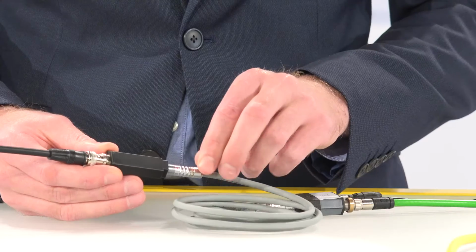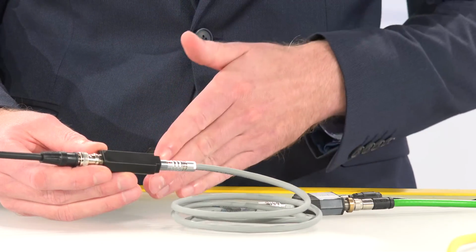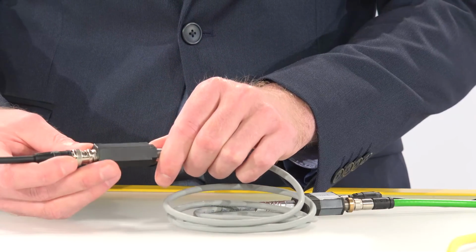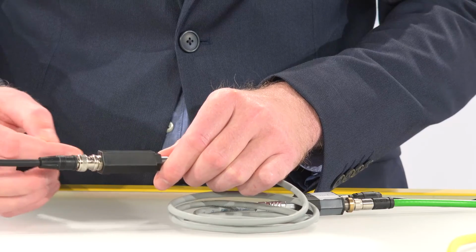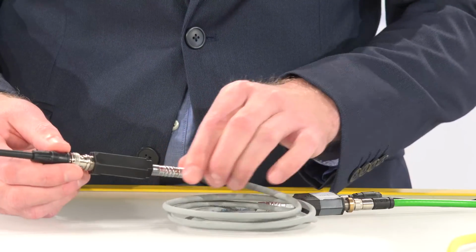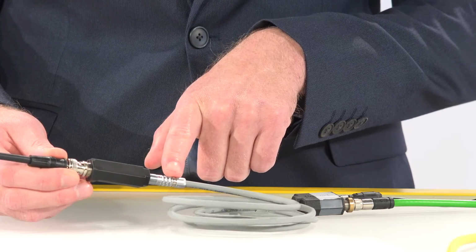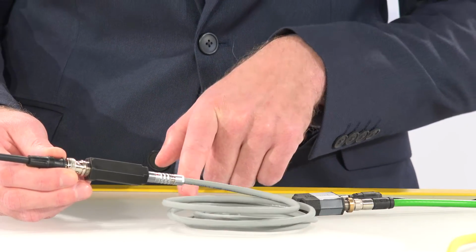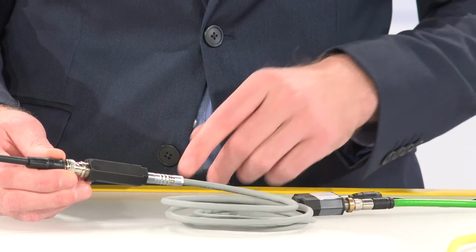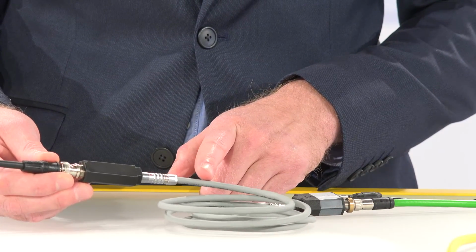designed at Perinet. In this setup, we have the simulator from the sensor provider, which provides the simulated signal of the pressure sensor based on this line here, and we attach the signal to one of our Perinet components, which are designed for this application directly. This Perinet component has an analog part where it gets the analog signal, and a digital output where it communicates the transformed analog signal to an Ethernet communication medium. We are especially using twisted pair Ethernet here.